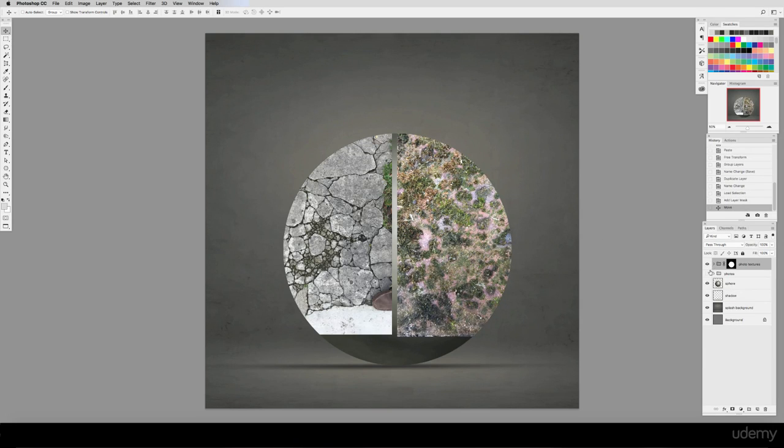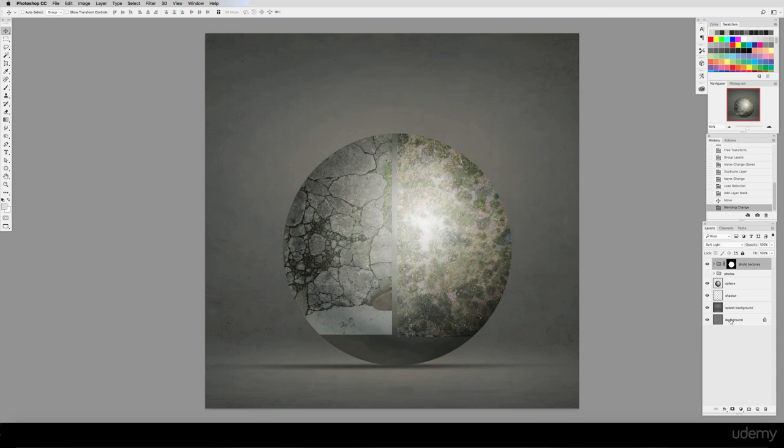Up next is the important part, so pay close attention to this step. With the photo texture layer group selected, we go to this drop-down menu which changes the layer blending mode. We then go down to Soft Light. As you can see, suddenly the photos interact with the sphere layer below in a whole different way. We can see the color and rendering form of the sphere below, but we are still getting all of this cool texture from the photo.